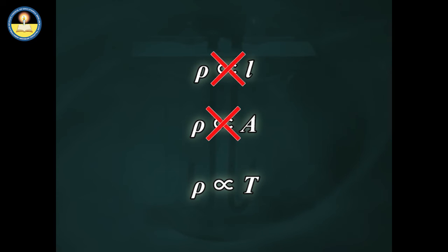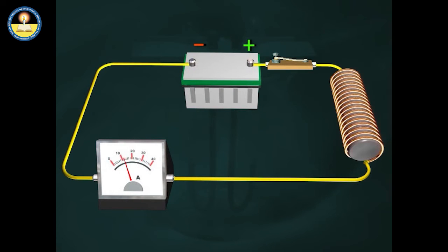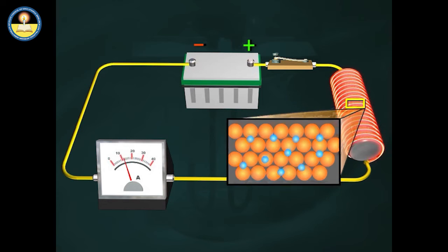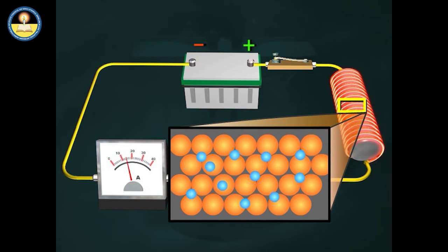Today, a replaceable fuse, that is, a cartridge fuse, is in use. When the fuse is blown off, it is replaced, rather than replacing its wire. Such types of fuses are used for domestic purposes and rated as 1 ampere, 2 ampere, 3 ampere, 5 ampere and so on.